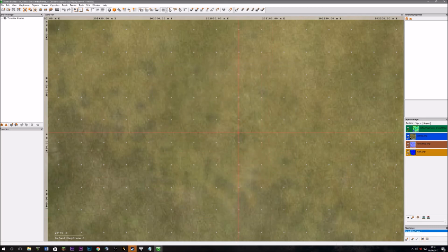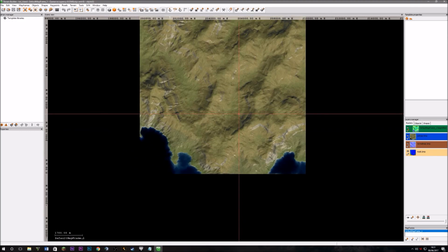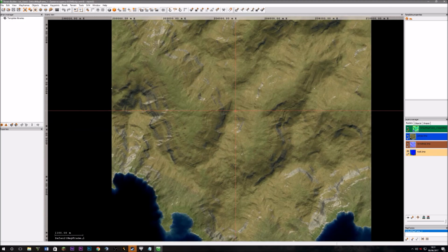Okay, so I've regenerated the layers now, and seems to be all good. By the way, you're gonna have to do this every single time you make an edit to either your satellite, your normal map, or your mask. Just to replace your mask, all you do is you remove it from the terrain, or same with the sat map, same with the normal, and you just import it over here and just drag it into the same order. Just make sure it's got the same coordinates as the other one and the same resolution. Should be all good. You just regenerate the layers and it's applied.